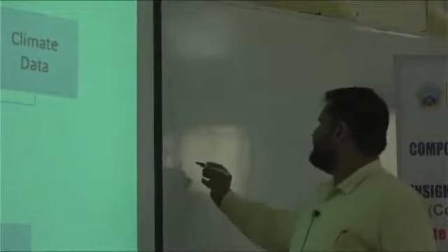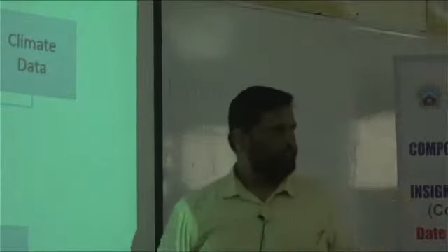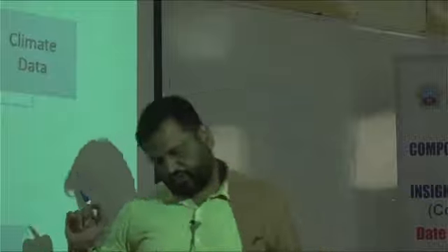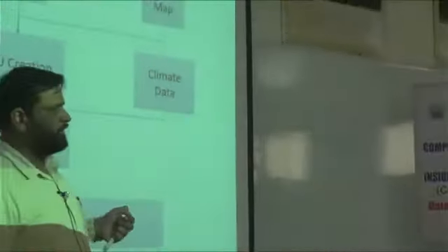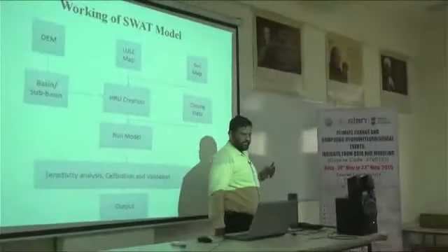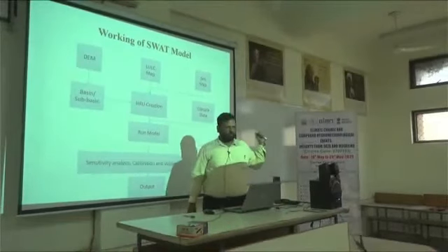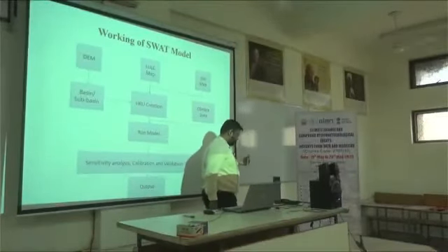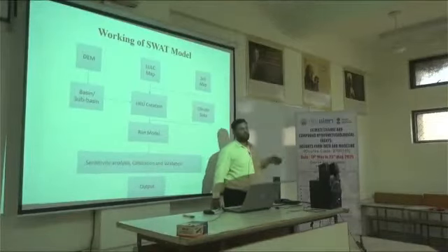Then the third input you require is your soil data. What you can do is directly use the soil map prepared by FAO, the Food and Agriculture Organization. They provide a raster image of soil data for the complete world, and with the help of that you can create your own soil database.